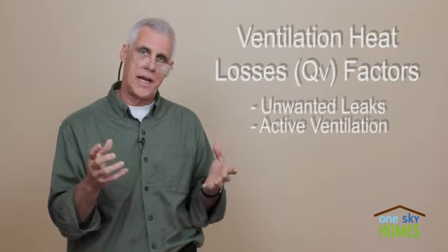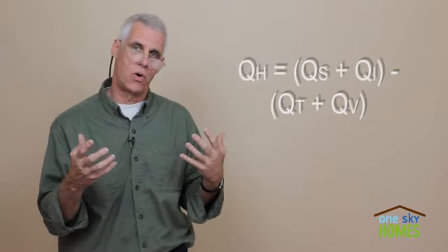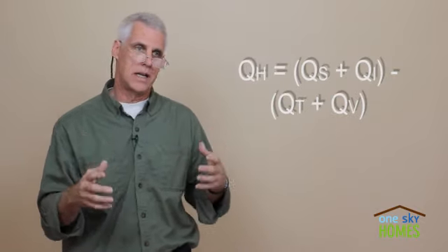So our wonderful equation here of passive gains minus passive losses that we solve for gives us this sort of intellectual framework and understanding where we can guide our design to begin with, and then use the Passive House Planning Package, the modeling tools, to solve for the equation and therefore minimize the amount of active energy we need to input into the building for either heating or cooling.